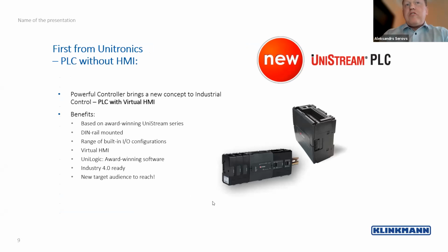What else is interesting in the UniStream series? New PLCs without HDMI. Of course, it has built-in virtual HDMI. We can connect to it using VNC protocol. So from your computer or maybe from your phone, you can over Wi-Fi networks, as example, connect to your PLC and use all possibilities of virtual HDMI.